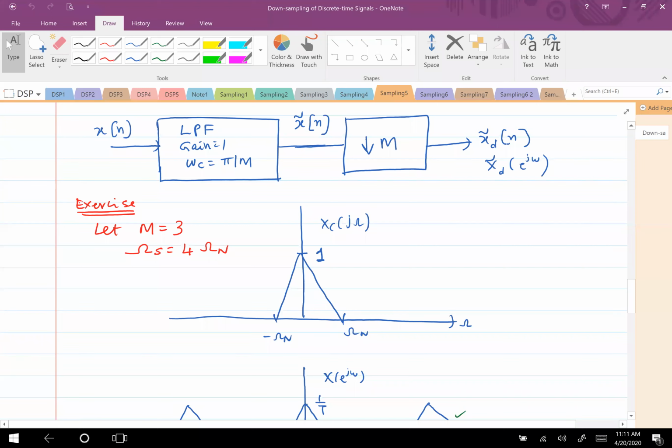So I repeat again: downsampling, if you try to interpret it from the viewpoint of a continuous time signal and compare it with the already existing discrete time signal. You have your impulse train, where the distance between any two impulses was, for example, T. Now it is T by 2 if you are downsampling by a factor of 2, right? So that would give you more copies of the same frequency spectrum the moment you are downsampling it.